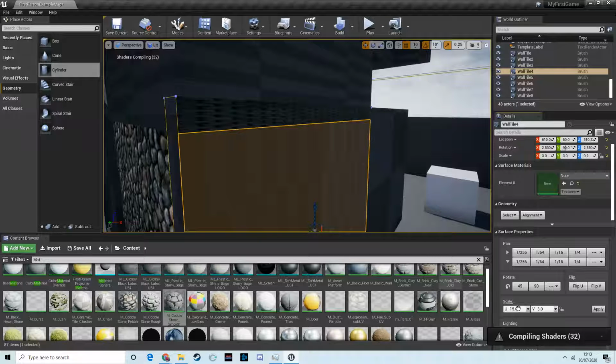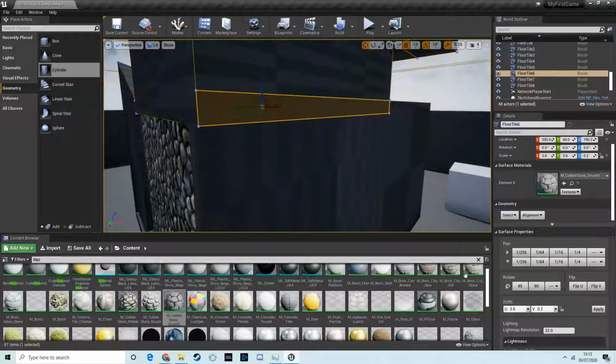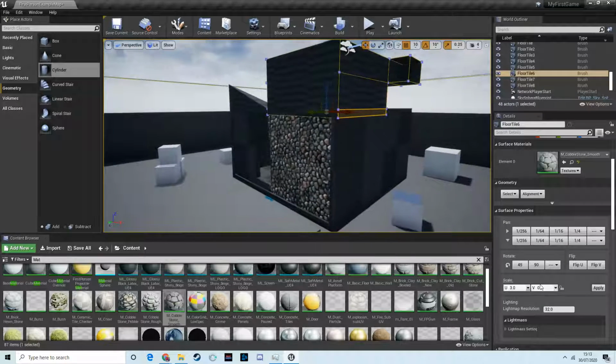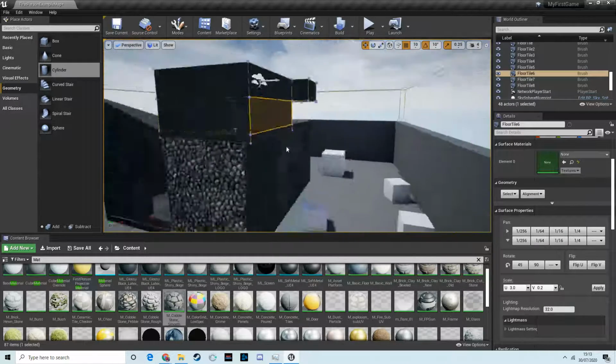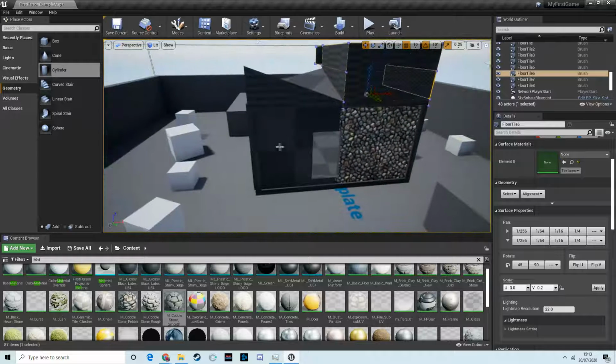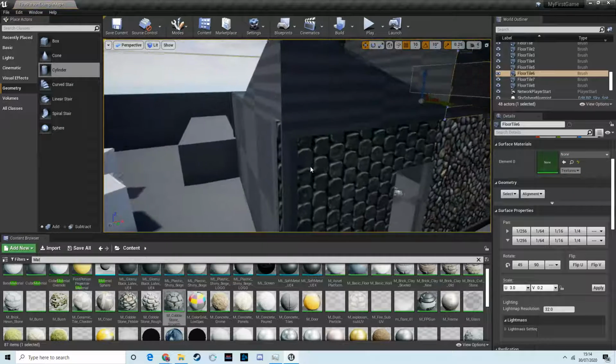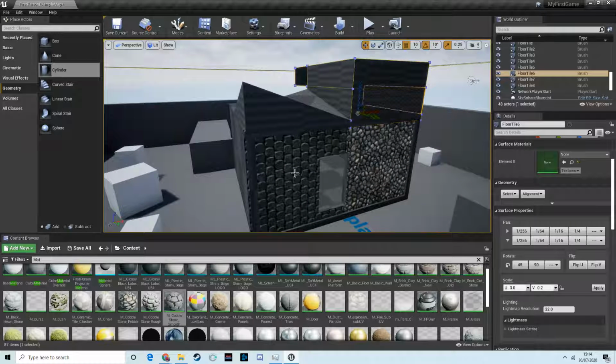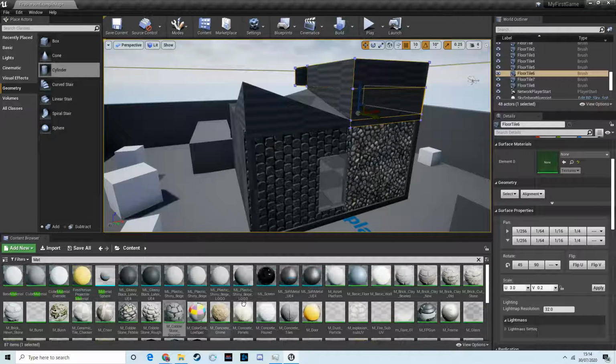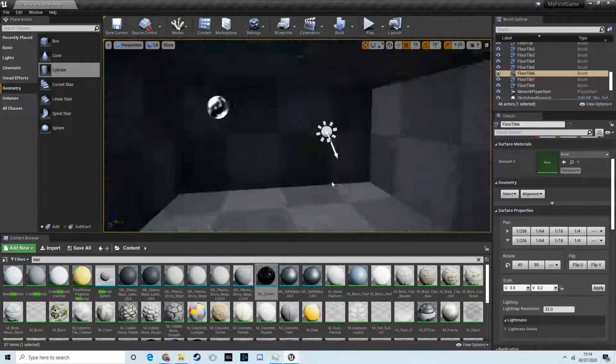that's going to take a little while, but that doesn't seem to have done anything. So I know you can mess around down here, but it's been a while since I've done any textures with BSPs. And like I say, generally the BSPs are only used for prototyping anyway. So you may find that you want to texture them just to give your prototype a cool look. But in general, you're going to be doing all your texturing and all your modeling in external programs, and bringing that stuff in. So play around with the different materials. Look how some are shiny, some are metallic, that kind of stuff.